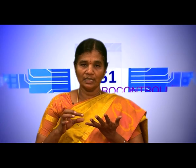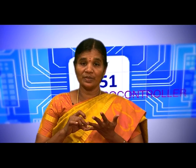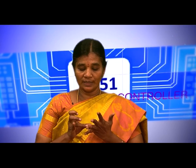In this way, when the SBUF is full or empty, the TI and RI will be activated to interrupt the microcontroller for read and write operations. This serial asynchronous communication supports different baud rates. The baud rate has to be loaded into the timer, and according to that the pulse width will vary. For that we most frequently use Timer 1, the TH1 register, with auto reload. For that we have to know how to calculate the baud rate.